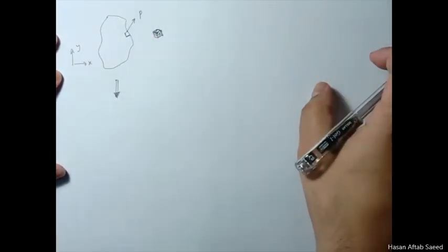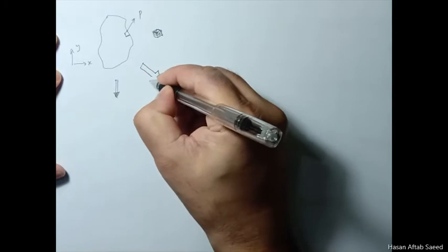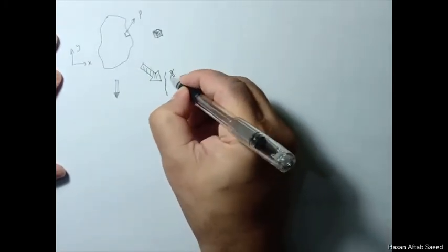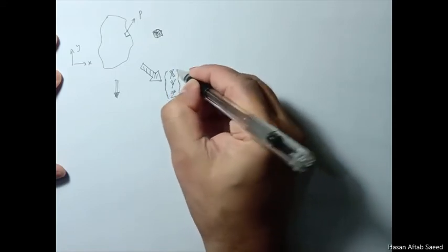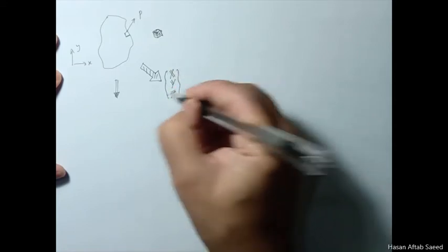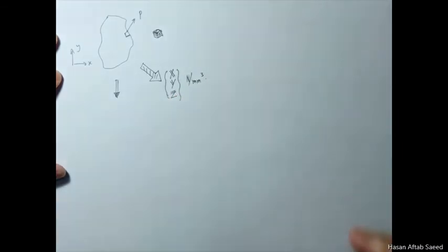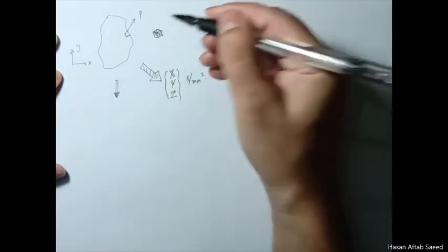But generally speaking, there could be magnetism, there could be any kind of body force, and it could have an arbitrary direction like this. In this case, let's call it a vector with this sort of loading, and the loading here will be in Newton per cubic millimeter, because when you multiply this with the cubic millimeters of this volume, you'll get newtons.